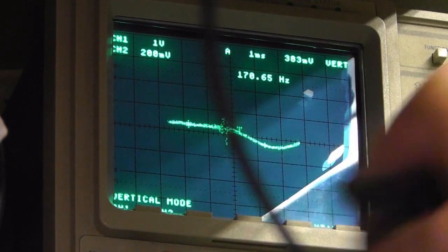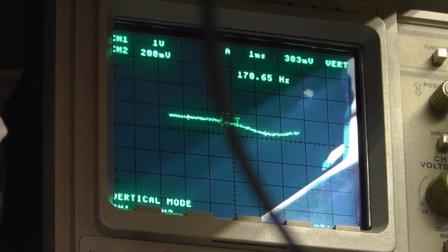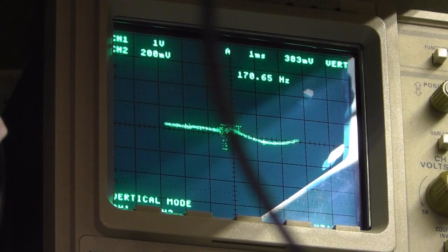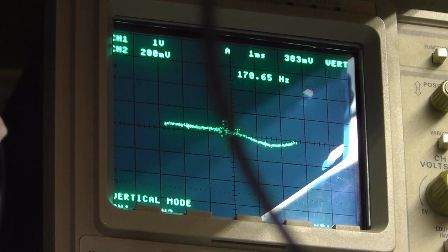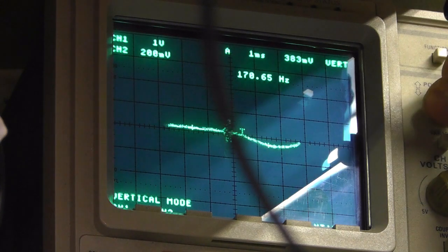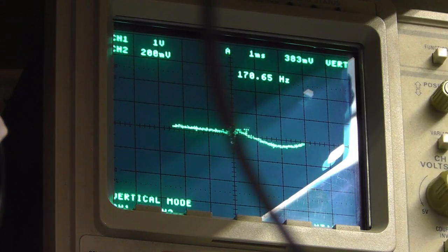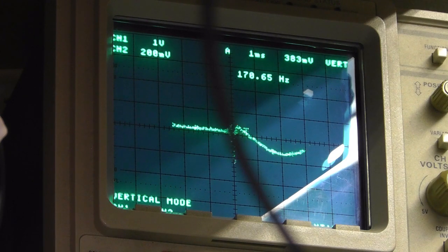So we've got our marker. We can see our markers. That's our 10.7 megahertz reference. It's useful also because if the Philips Wobbulator drifts slightly, we still know our reference point. So we'll get that centered, and now we're going to put the minimum amount of signal in, which I've basically got. I'm just turning the volume up a bit now, and we're going to see if we can improve this signal, with quite a low drive at the moment.